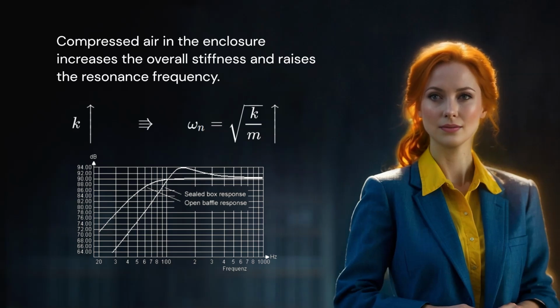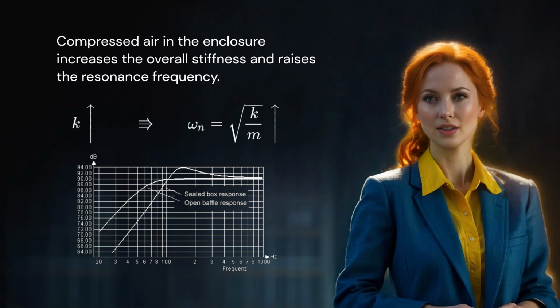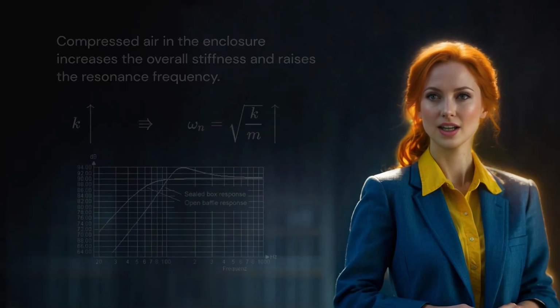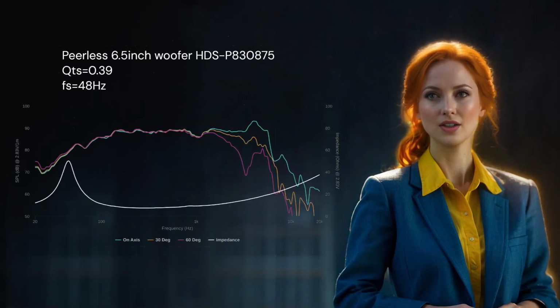The additional stiffness by the air in the box could also result in more pronounced excitation of the cone, requiring tighter control from damping. Therefore, the driver unit is typically overdamped, beyond what would be optimal in free air installations such as on an infinite baffle, to compensate for the strengthened resonance when the driver is mounted on an enclosed box.